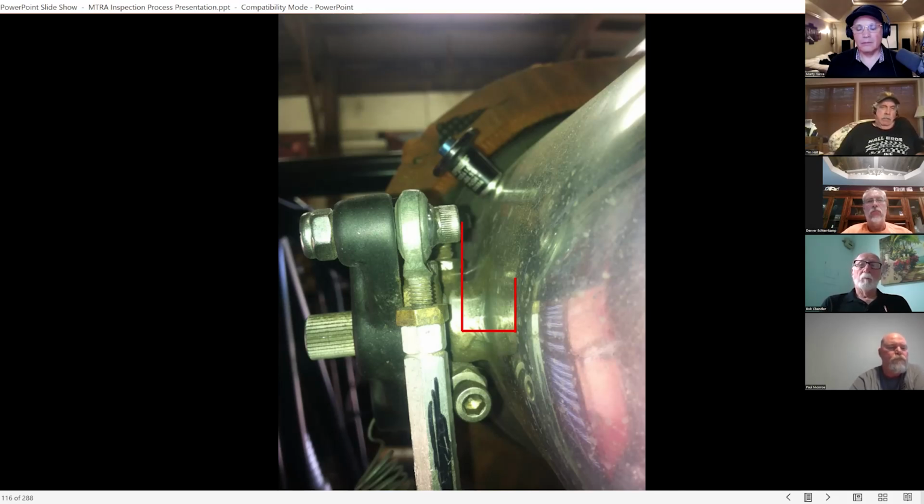When you look at it, that's the way Enderle puts them together, or used to put them together. It's extremely common, more common than you think, to see that screw in there without a nut on it. They just screw into that threaded black arm, and it'll back out and bite you when it gets into that injector hat. Best to put a screw and nut on it like this one has, so that it's essentially double nutted, because there are threads in that black arm and then the nut is on the end so it can't back out, or put the bolt in the other way with a nut on it.